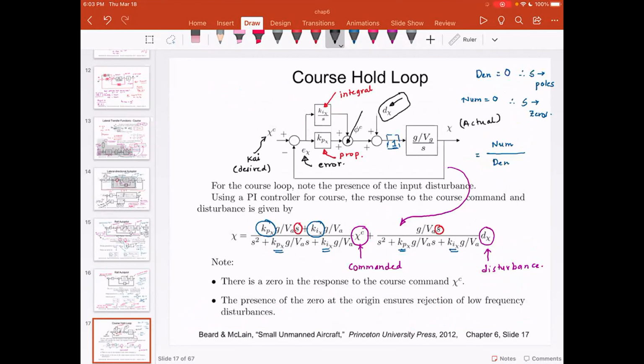If you look at the path the UAV is taking, if you draw a tangent, the angle between the path and the direction in which the UAV is headed is nothing but the course. Now, if you look at the expression for the course, I want you to look at this particular part of the transfer function. This says phi c, so this is the commanded phi.